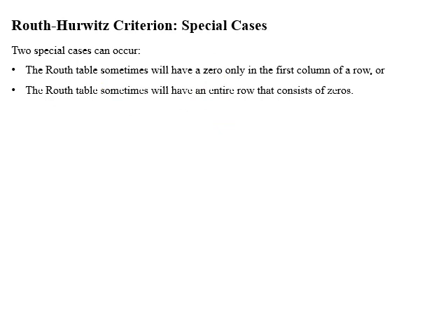Dear students, we are studying stability of a closed loop system with the help of Routh Hurwitz criteria. This method consists of two steps. In first step, we design a Routh table, and in second step, we interpret the table, through which we find out distribution of poles. In this method, few special cases also occur while computing the Routh table.